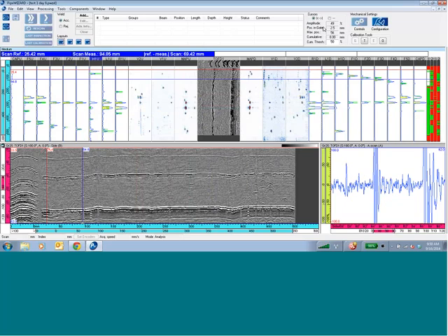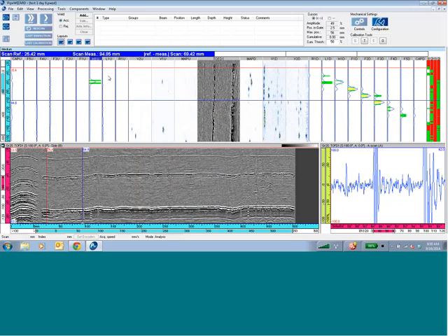This reflector has 49% amplitude. It's going to give me the position in the gate, depending on the size of the gate. It gives me the position in the scan axis, so we can see how that lines up with about 50 millimeters. I get that information very quickly. And then by looking at the color, I'm able to see the relative amplitude. So these are the types of tools, the color coding, the height of the bar, as well as the quick information here, that allow the zone discrimination analysis to happen very quickly.